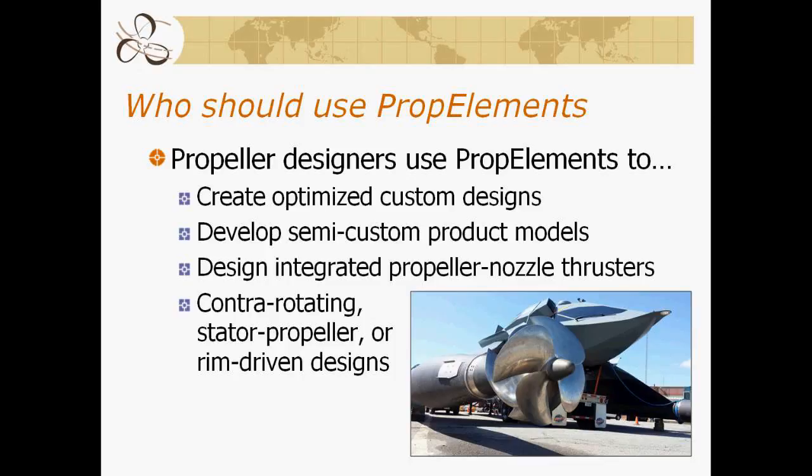At this point, the lift and drag calculations and the performance are subcavitating. We can represent the expectations of cavitation, but right now there's no correction for performance change if we get into very high thrust loading. Duoprop is an outboard style small propeller, often runs in a mode that would be well modeled by PropElements. But I just want to make it clear that if you get into very, very high blade thrust loading, you might exceed the scope of PropElements in its version right now.